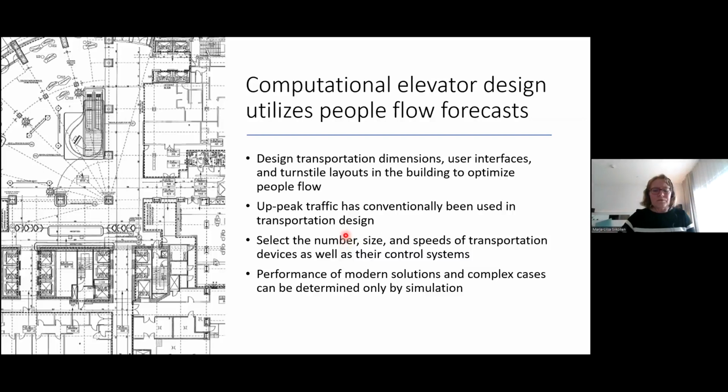Before software-based control systems, only up-peak traffic situation was used in the elevator planning. But when we got more sophisticated control systems with software, we couldn't anymore find out the performance from up peak only. So we had to simulate the traffic in the building to see how well they can handle different traffic situations.